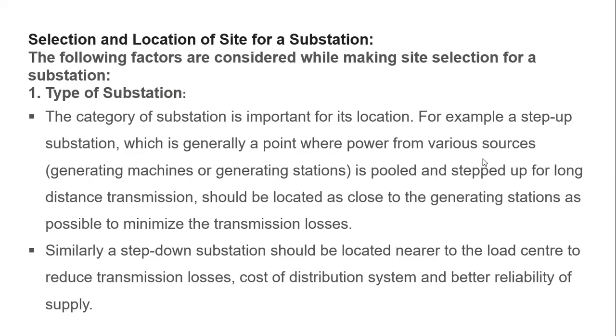Okay, suppose we are installing the step-up substation. Step-up substation means that generally we are having the generating stations and various power sources. For step-up of that long distance transmission, it should be located near to the generating stations. Therefore, we minimize the transmission losses.